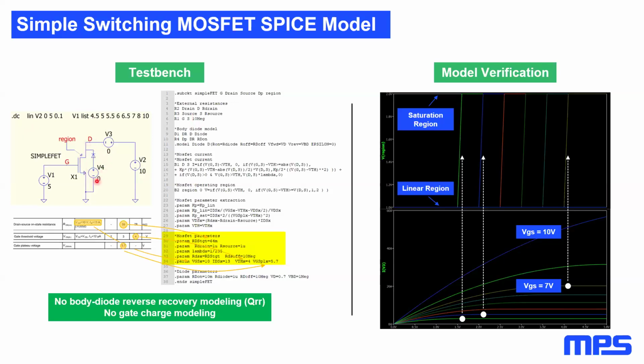In practice, this has a piecewise characteristics where the breakdown, the off, and the on regions are associated to a resistive linear behavior, and these regions are connected by a quadratic law. These diode model parameters can be extracted and refined, relying on the data available in the datasheet. In our case, we use the diode characteristic graphs.